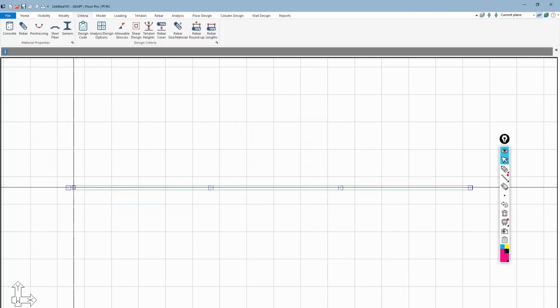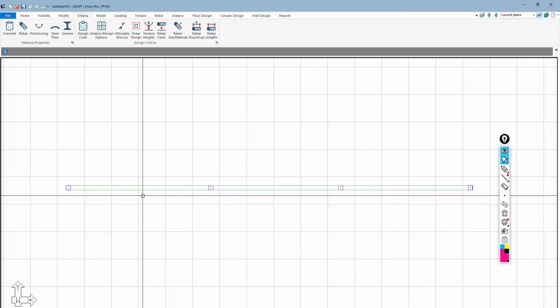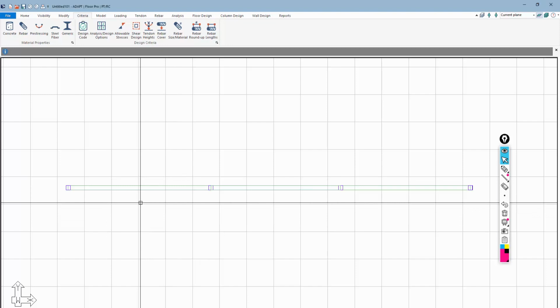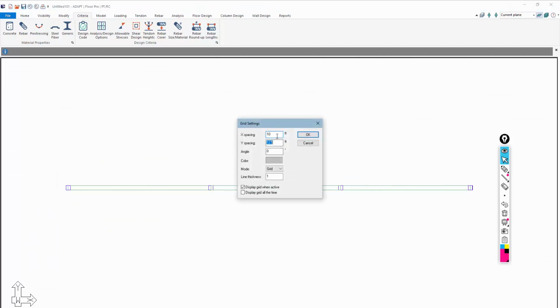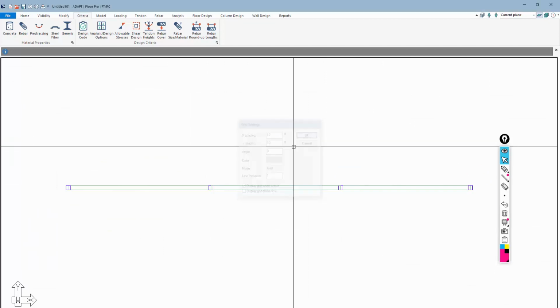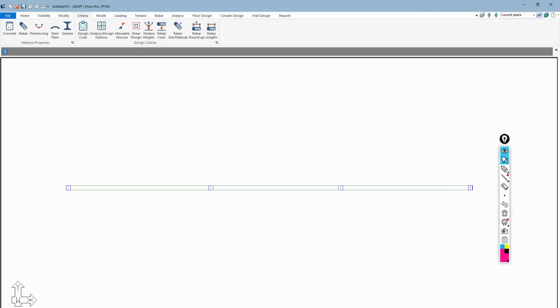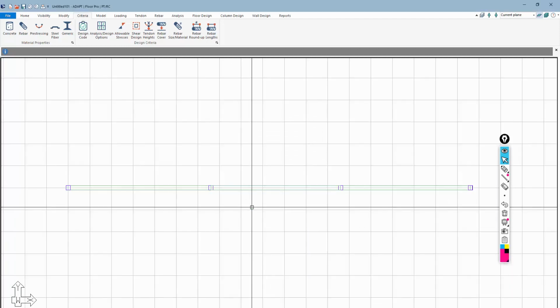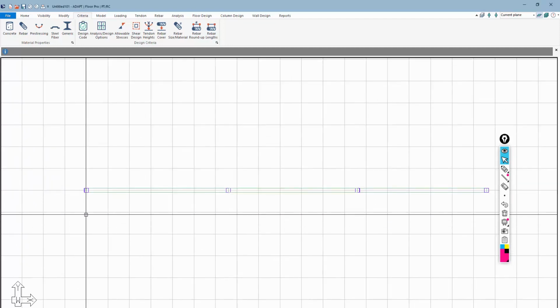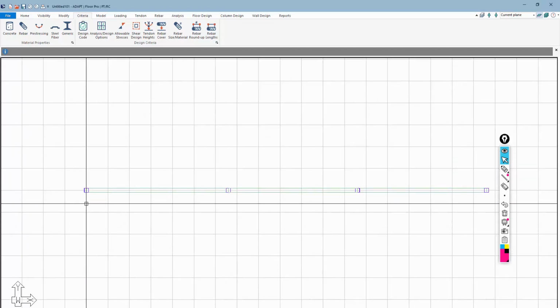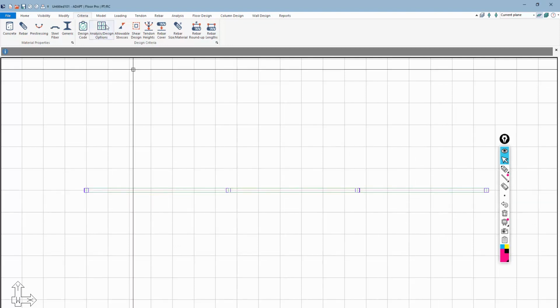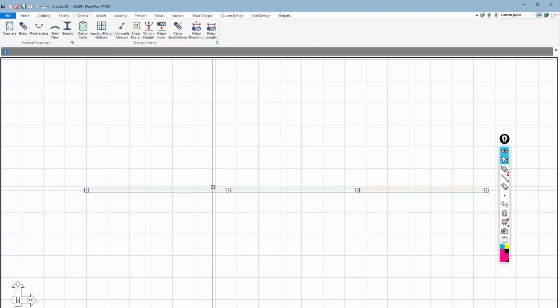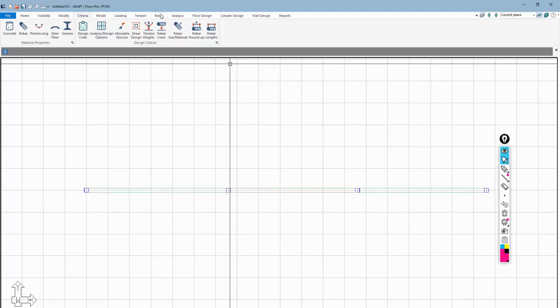You'll notice when I do that, this is actually not centered on that grid. So this actually may not be as helpful either. So let's go back and let's just make this flange divisible by 10, because that's kind of where we had started our columns. All right, let me turn this grid back on. All right, so we have 10 feet this way, 10 feet that way. We're going to make this flange, let's say, 240 inches. Okay, so now because this is stepped, I actually need to create 3 unique slab regions.